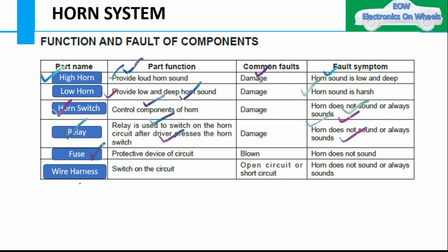Now the fuse. The fuse function is as a protective device of the circuit, and there might be cases that it will be blown, right? If it is blown, then the horn does not sound because it will make an open circuit. Correct. There will be no current flow.